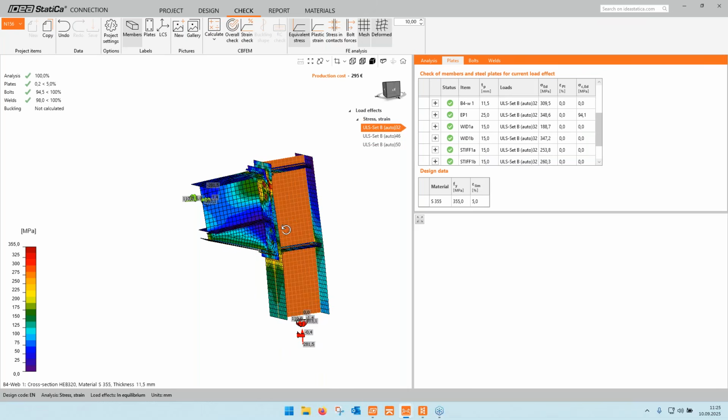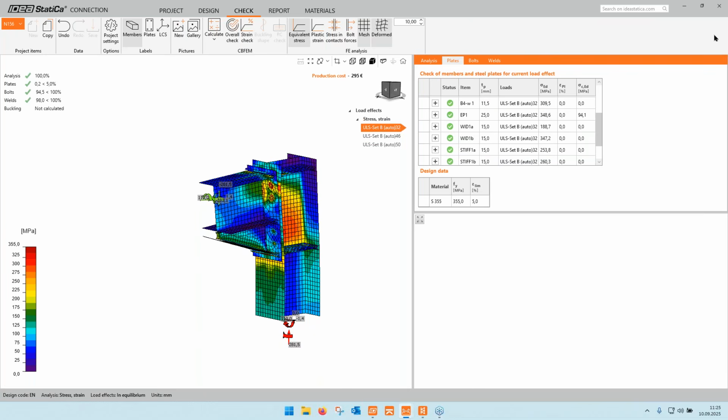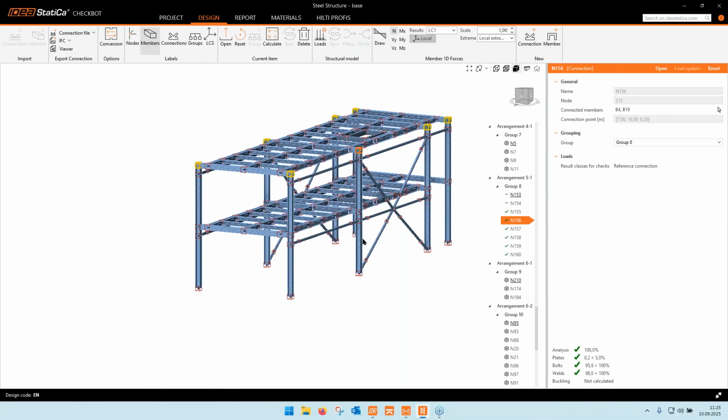And if I say, yeah, that looks good, I agree with the results, I don't need to change anything because the code checks are passed, I can close this node and proceed with the next step of the workflow. But before we do this, what I mentioned here is that for the reference node, you are adding the operations and also choosing which analysis step shall be run.